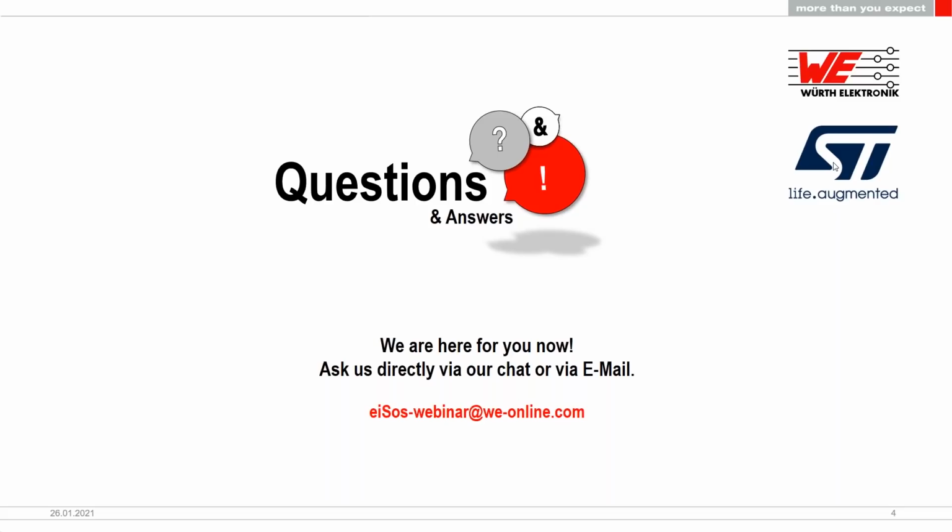Okay, so two cases. For the 5-volt only device, the 45L, it's straightforward. It needs no customization because it's fitted to a limited number of use cases at 5 volt. And for the high voltage one, the 4500, it can be configured either through a non-volatile memory or by software. For the non-volatile memory, you have a graphical user interface, or some dedicated software to run during the manufacturing phases, and it takes about 40 bytes of I2C words. It can also be done at any time from an application MCU in order to align the USB PD port profile and application requirements, for instance.